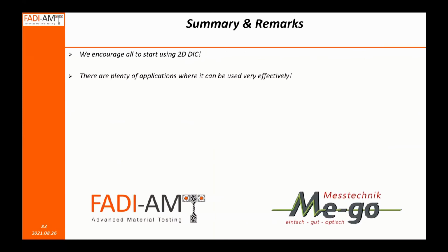We wanted to end this webinar by saying we encourage you all to start using DIC, even if it is 2D. There are plenty of applications, even though they're planar. That's not a major restriction. 90% of the tests that people do on a daily basis are done on a tension machine, which tells you that most of your tests are planar in the first place. So what's the problem? We have a lot of applications where we can use it.